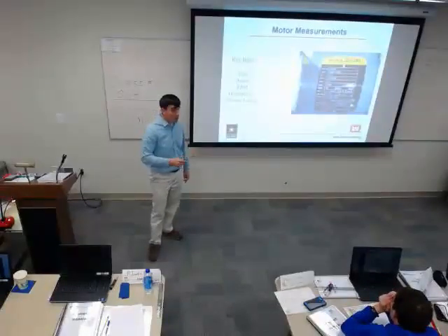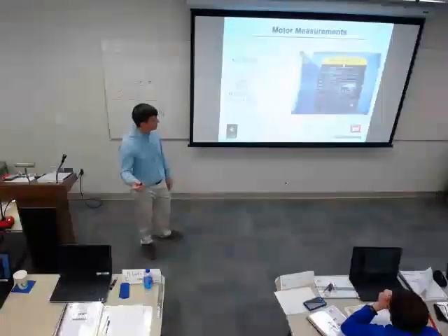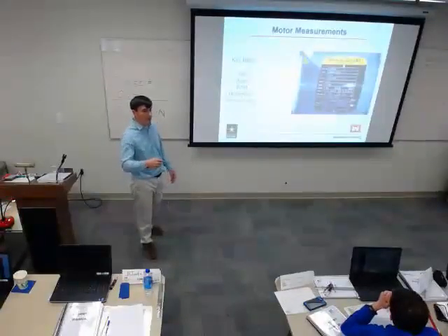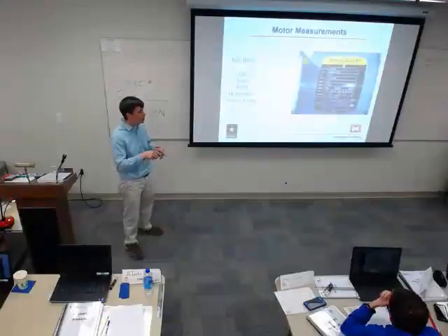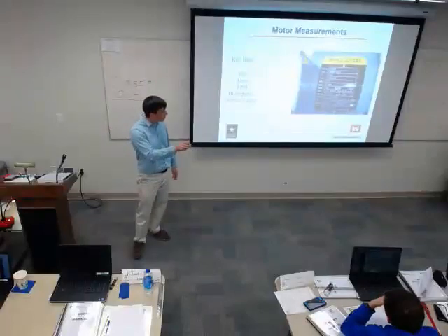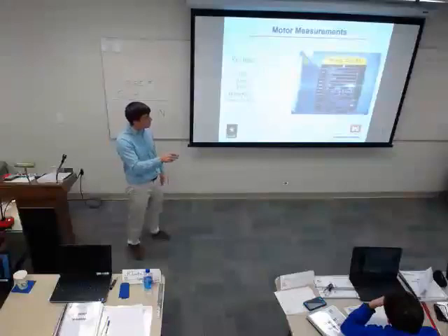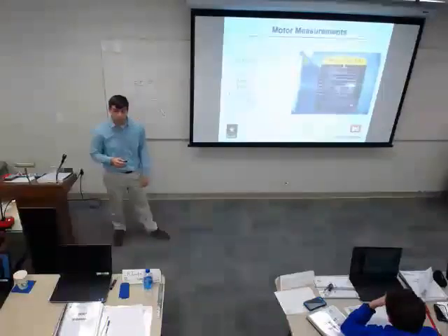You need to make sure which voltage you're operating at. This one says 230 and 460. What does that mean? It can operate at either one of those voltages. It's got different taps on it, depending on what voltage your system's going to be. And correspondingly, the amps: if I'm running at 230, it can go up to 2 amps. If I'm running at 460, it can only go to 1 amp.